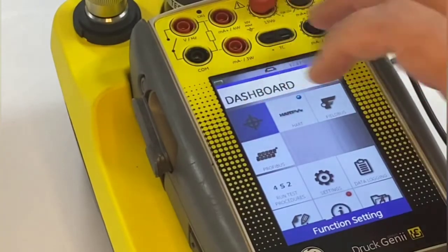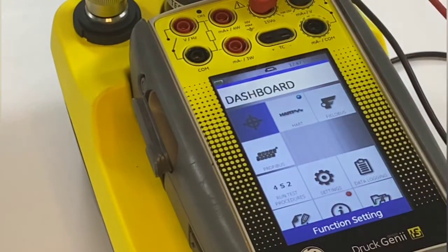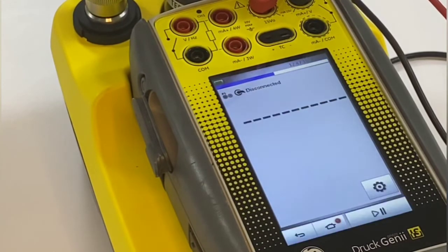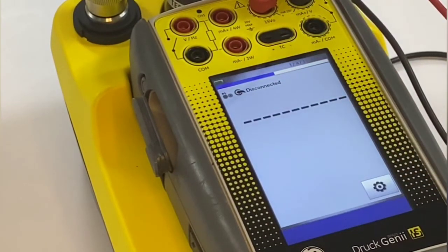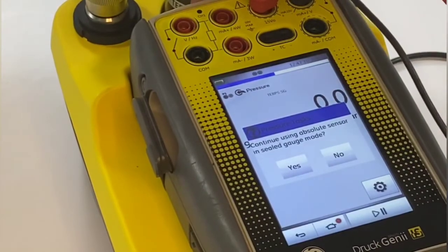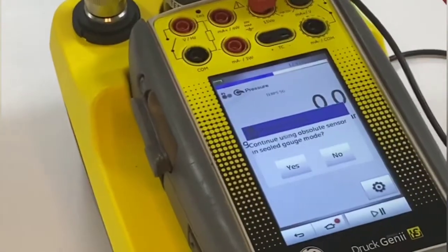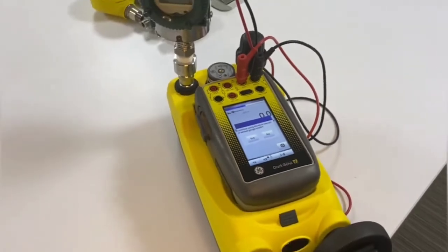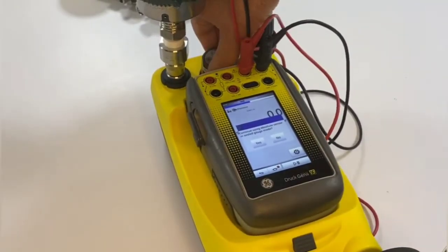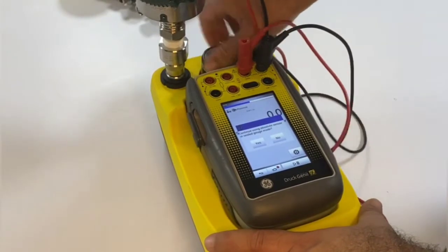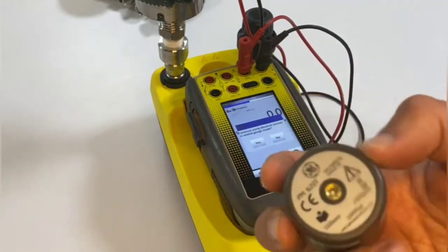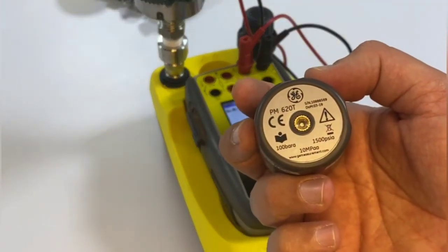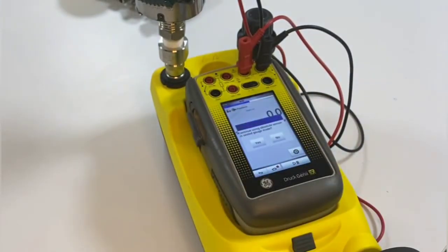So this is the same you can do from the calibration task, but the calibration will do the task without documenting that. Our purpose is to perform the documentation into the 4Sight software. So here is the pressure module I'm using. Of course, I'm using the PV622 pressure station, which can generate from vacuum to 100 bar. And I'm using the high accuracy pressure module, the TERPS module, range of 100 bar absolute, or 99 bar gauge.